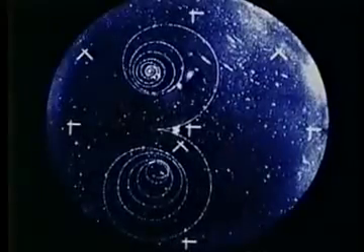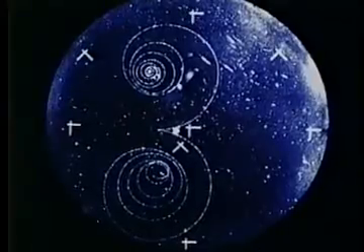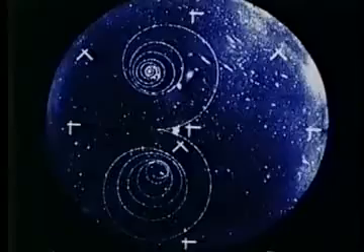Still another example of cavitation occurs in the type of bubble chamber used for studies of high-energy nuclear particles. In this photograph, a positron-electron pair has produced a track of bubbles in liquid hydrogen, which is at a pressure below the boiling point and is therefore unstable. We have seen that cavitation can take several forms: small transient bubbles, large, more or less steady cavities, non-stationary cavities, and often a mixture of these types.